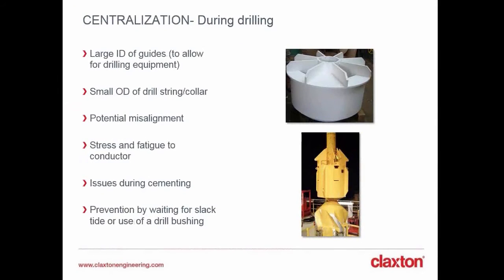As I mentioned before, centralization is a key issue for the structural integrity of conductors. What you have is a big clearance between the conductor guides and the drill string once you first drill the wells, which would mean potential issues with the centralization during spudding. And that could end up translating into considerable misalignment between your drilled hole and the conductor guides.